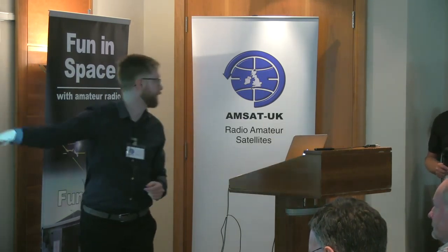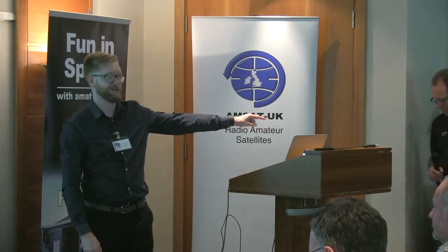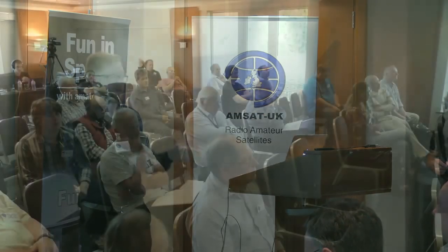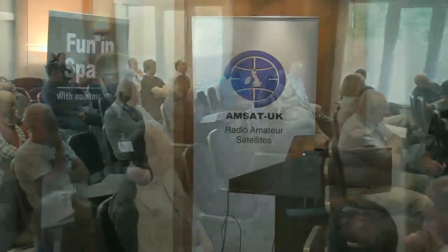And if you wanted to, you can decimate even further. So even though you're bringing it in at 2 meg, and you're looking for a 1K2 signal, or if it's a pager, even less, then you can just decimate it right the way down, or even just not sample as hard. So I can double click on a block and go, actually I don't need 2 megasamples. I only want 50K, or pick something that typically falls on a 32-bit boundary that's nice for a processor to utilize. So, yeah.